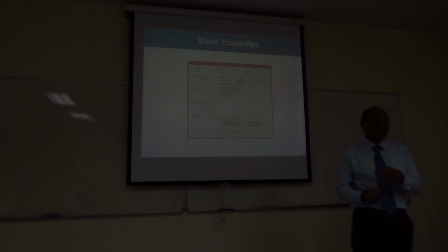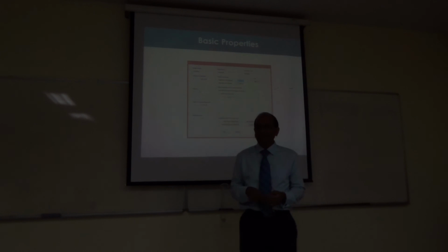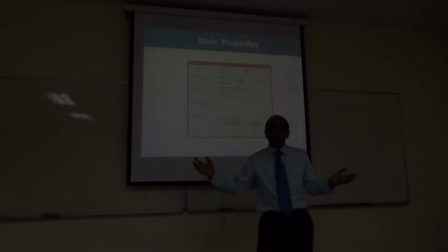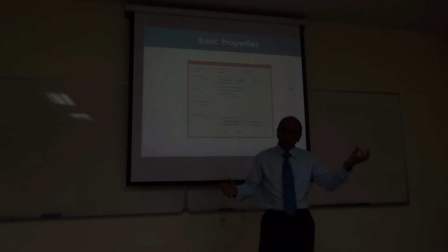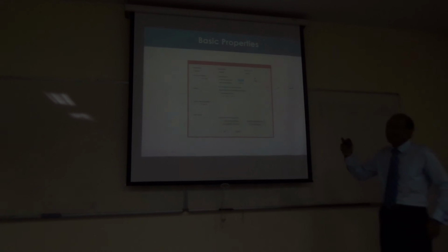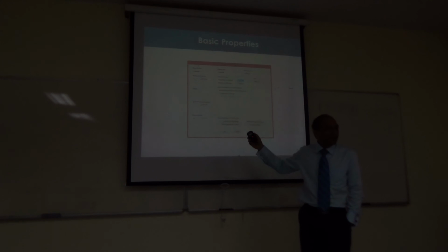Then it talks about anisotropic material, it talks about the orthotropic material. So really speaking, there are about 16, 17 forms, big ones, which need to be filled up before you can define one material completely for the analysis if you want to do a sophisticated analysis. If not, you can just give modulus of elasticity E and you're done, right? So the difference between simple material and full definition of material is huge. One value against hundreds of values, right? So I'll just show you, just for you to get an idea why we need to study all of this, because actually it is needed in the analysis. If you want to do sophisticated or complete analysis, this information will be needed.